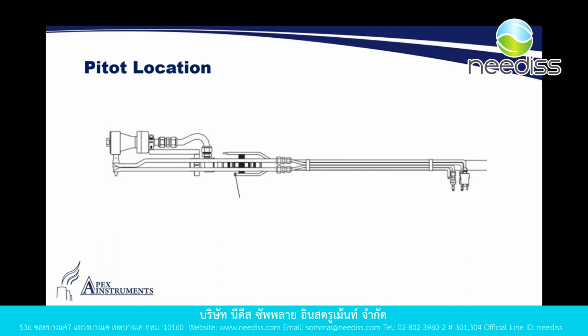But please keep in mind, if you're looking to require a PM cyclone now or in the future for your customers to do the sampling, that we supply you the correct pitot to accompany your cyclone, so you can meet the method to the exact standards. And keep in mind that if you do a combination of PM10 and 2.5 together, that pitot length will be different than if you do only a PM10 cyclone, because the PM10 cyclone will obviously only be this section of that whole system.